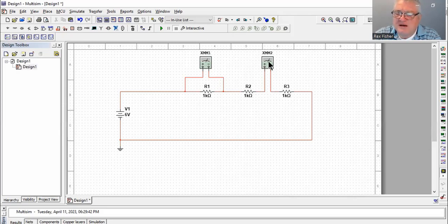So the closer we can get to zero, the better. If you buy a cheap meter, it'll probably have a resistance that's a little higher than a more expensive one. Over here, we would like our internal resistance to be a gazillion ohms, right? But in reality, they're probably going to be about 10 million ohms for a decent voltmeter.